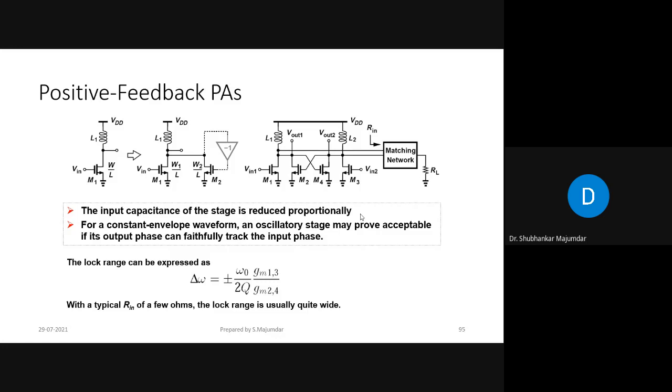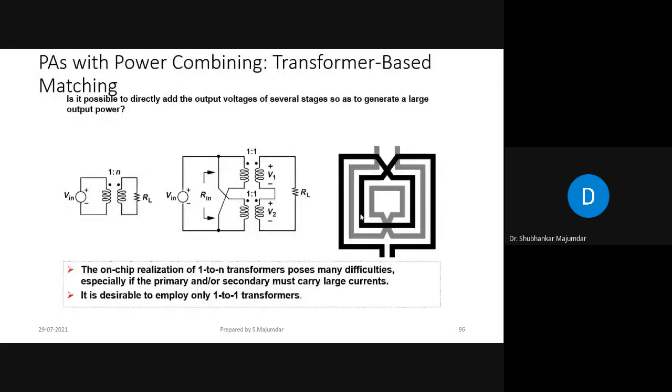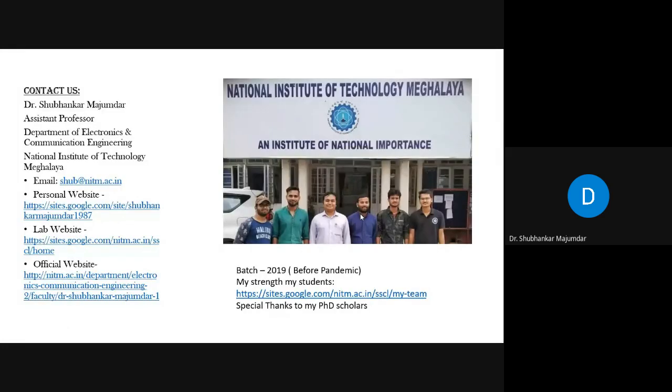They have free shuttle technologies also. You can come up with your own IC if they accept your design. It's a free PDK. You can download it and make the circuit in any tool like freeware, ngSpice, or anywhere.